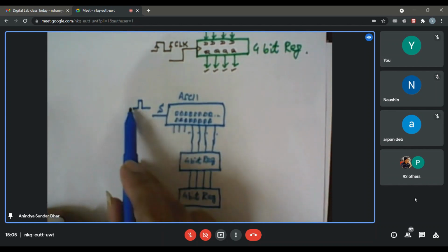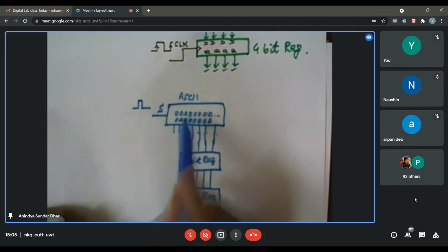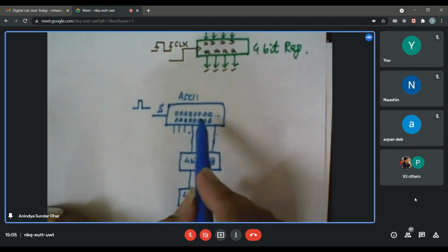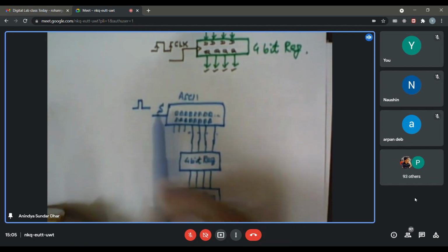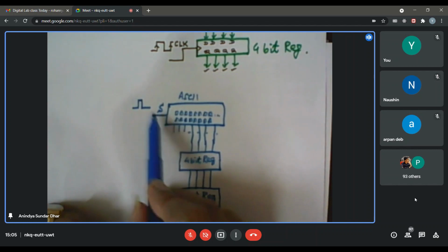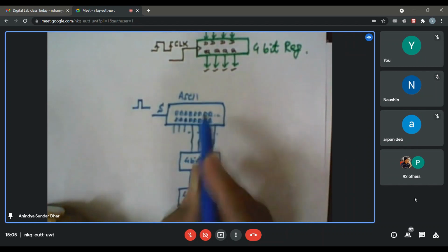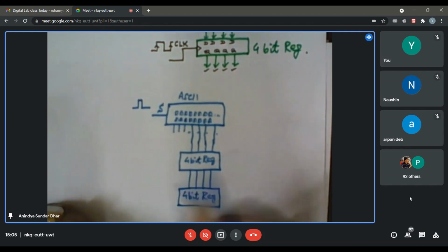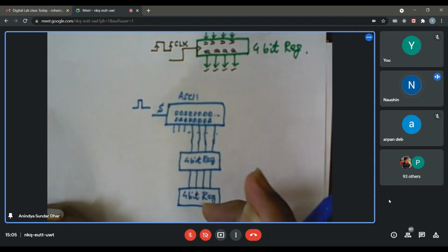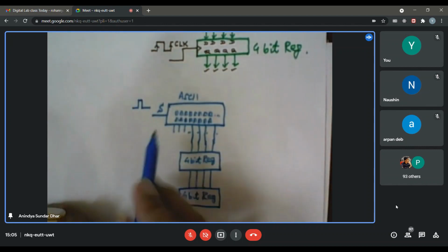Whenever I observe a pulse at the strobe output, I know that okay, the user has pressed a new key. So the strobe signal can be used for different purposes, but as such, if I find a pulse over here, I know that the user just now has pressed a key or rather released a key. So whether that answered your question? Yes, sir.